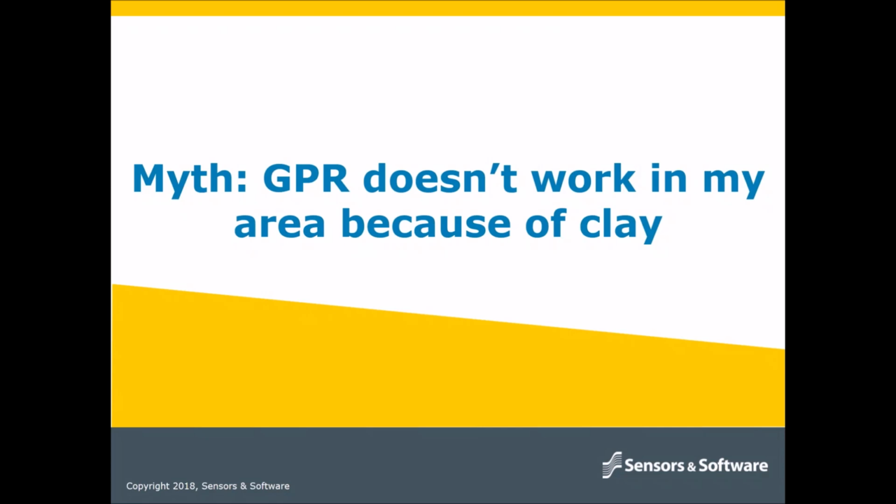So what does this mean for a utility locator? Well, GPR can still find gas, electric, telecom, and irrigation lines, to name a few. It usually can't find water, which is buried a little bit deeper below the frost line, or sewers, which are usually around 8 feet deep. So does GPR work in my area where there is clay? Sure it does, but it's important to understand the limitations of what it can and can't find.